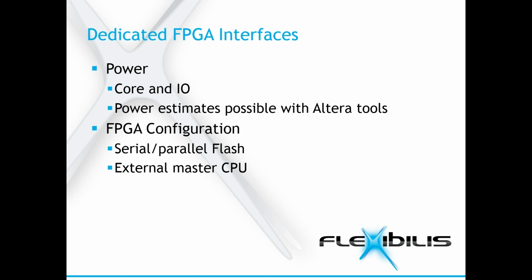The software and the FPGA configuration bit stream can also be distributed together, which guarantees that the software version used is always compatible with the FPGA configuration version. In some cases, for example when using PCI Express, the FPGA functionality has to be up fast after power-up. This forces to use FPGA configuration methods that are fast enough.